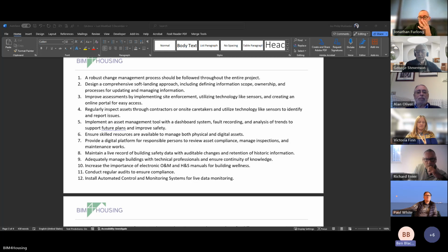I would say that an alternate grounding level on a lift should absolutely be captured in your cause and effect matrix. Absolutely, but it's not. But that's what I mean, it's only right at handover. What it does at grounding should be captured in the fire strategy and in your cause and effect. And then the question I think here is, when that changes, how do you know it changes? So back to George's point, that you keep your information correct and up to date.